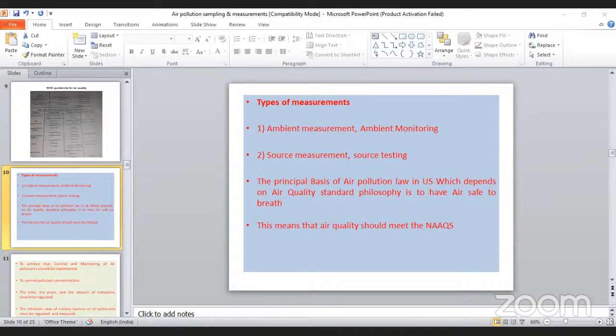Some of the chemicals will be highly volatile. If those volatile matter may escape, for that reason they provide a sequence of impinger bottles. If it is not dissolved in one bottle, in another bottle it may be dissolved due to the temperature difference. Like that, the arrangement is made. Here, the most important thing in the impinger is the sampling solution, or we can say solvent or water. Impingers are glass bubble tubes designed for the collection of airborne particles into a liquid medium.